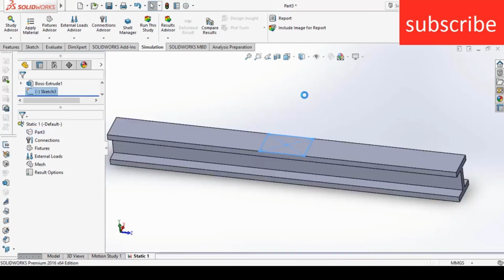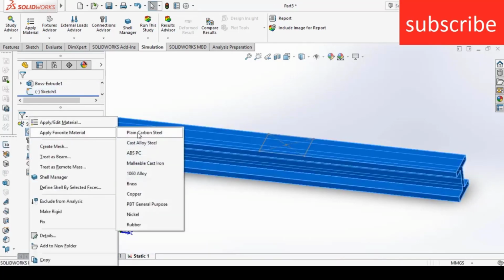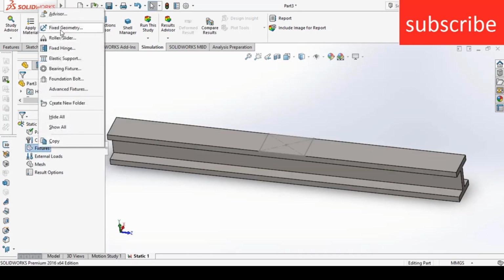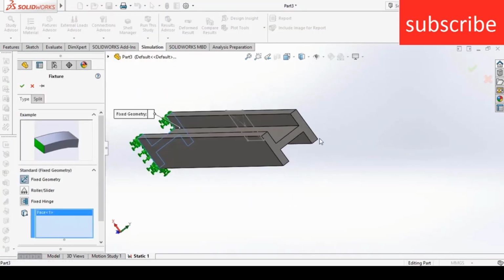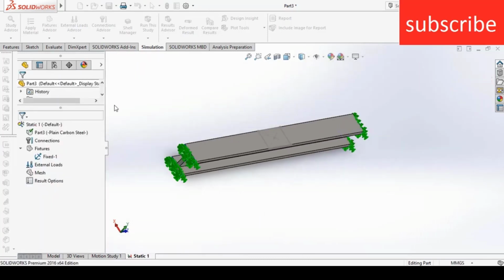First exit the sketch. Now click on part, click on apply favorite material, click plain carbon steel. After that go to fixture basic, click on fixed geometry, select this face and this face, click OK.